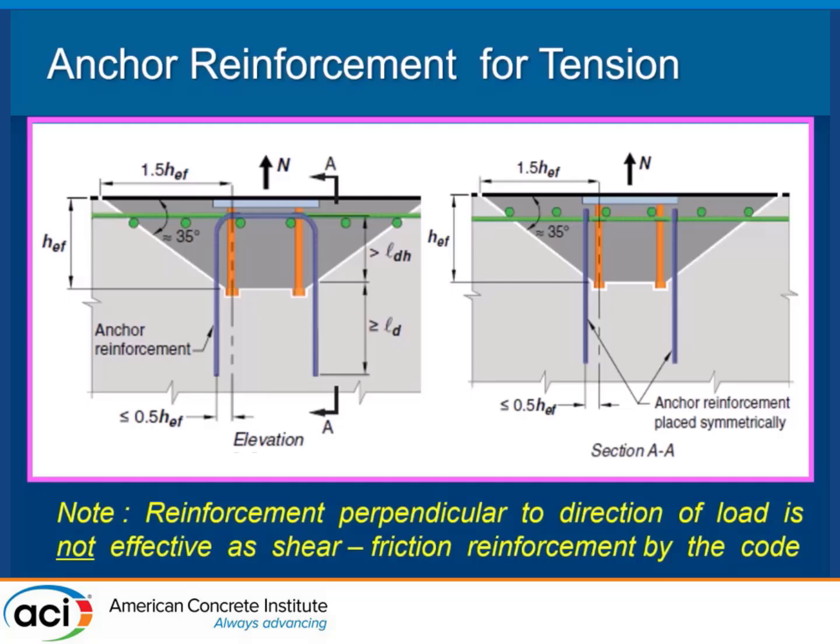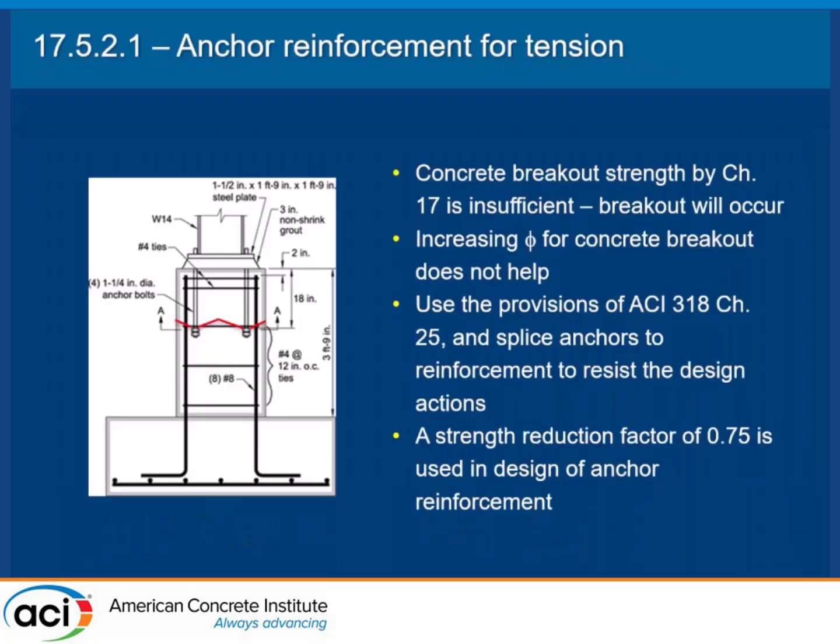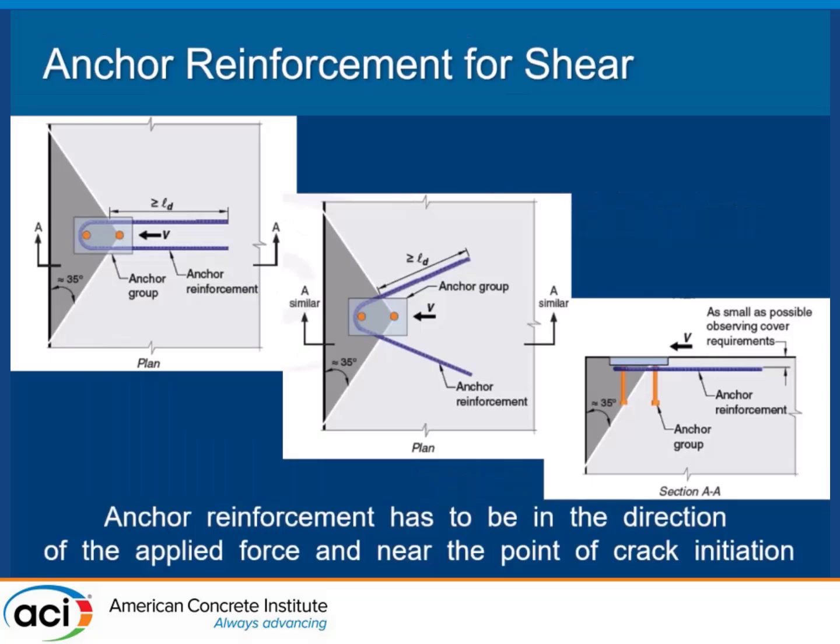However you do it, it almost makes a little more sense in shear, which we'll get into a little bit more, so don't worry about that. Shear is a little different, but the point I want to make here is, like in shear on the edge of a slab, I typically have an edge bar, right? And then I'd probably have some mat steel coming over, and it would be hooking down, right? Well, I'm just going to have that there anyway. I'm putting this thing in here.